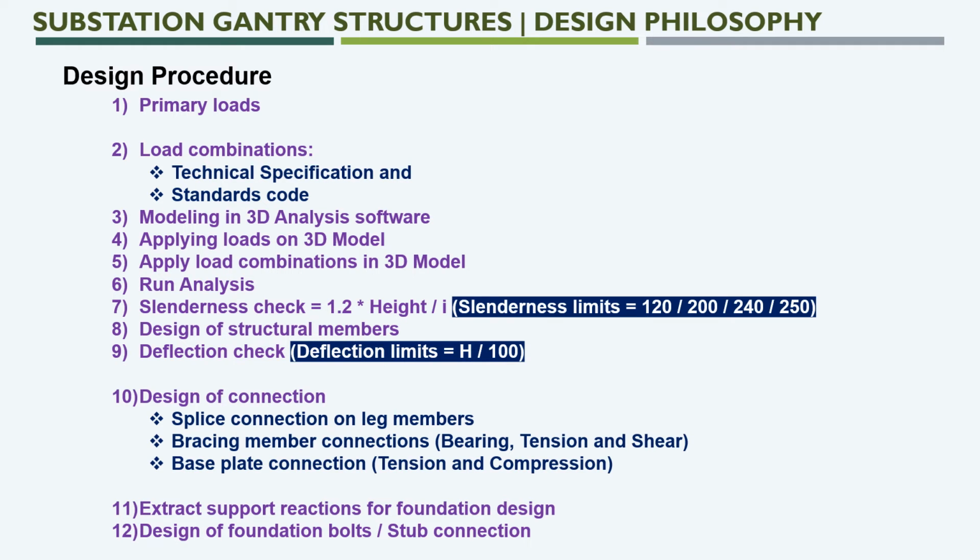It will just break the main leg span into 2 or 3. And another one is the horizontal beam. Generally this will have a tie between the main legs in the horizontal direction, so it is not in inclined form. This will have 250 as the slenderness limit. Likewise we need to check it.